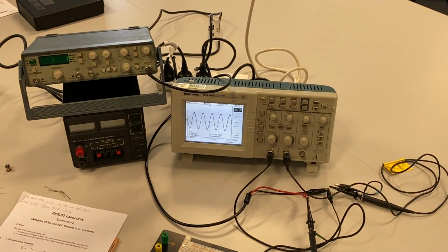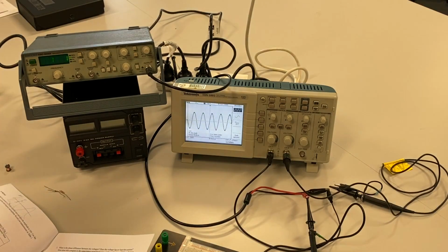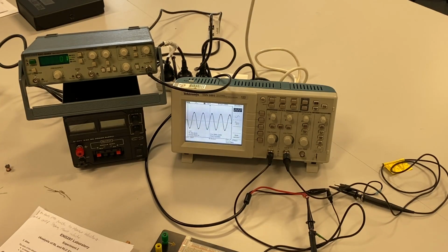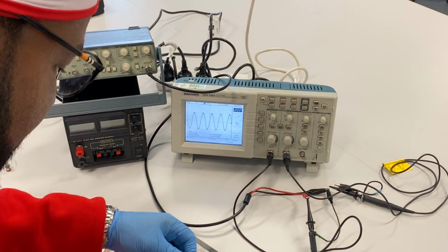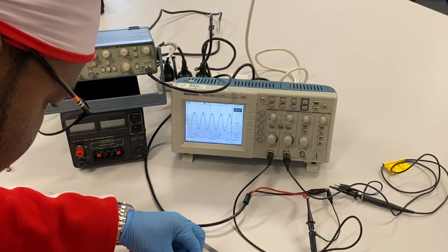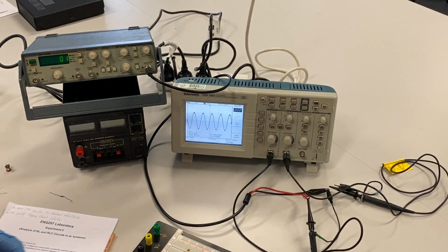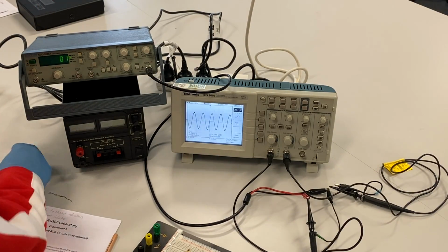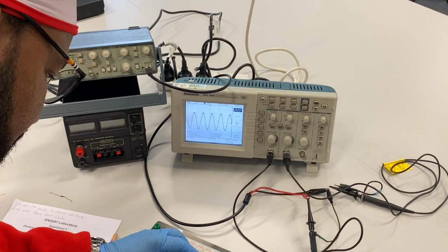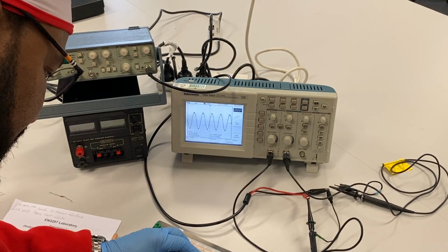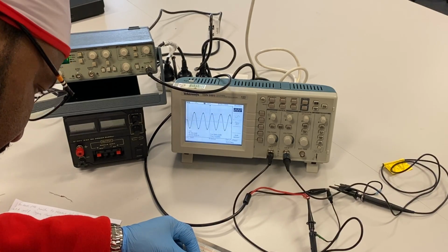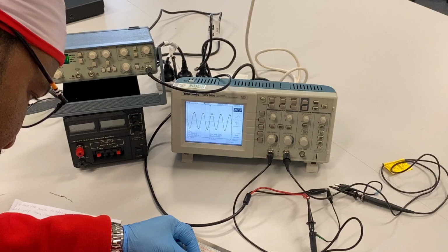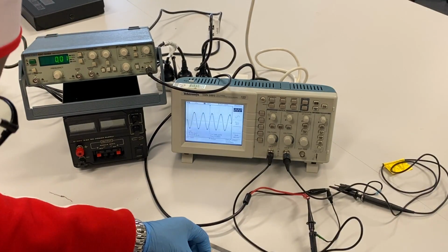Let's see. Quickly, the first thing you say is build the circuit in figure 1, right? So it has a 1 kilo ohm resistor. I just take the 1 kilo ohm resistor and put it here, like that. Then I create a node there to put the 10 millihenry inductor. Let me just create this node, right? I create that node, 10 millihenry inductor.